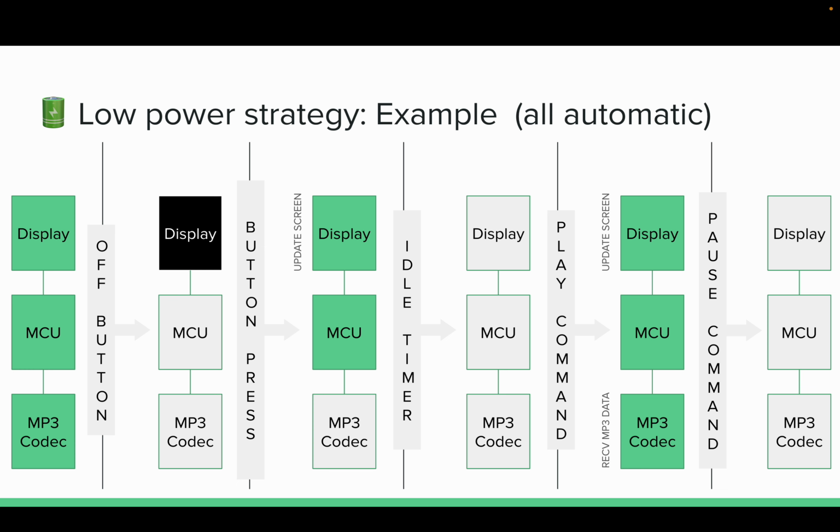Basically, it updates the screen. The act of trying to update the screen will do the work of the driver going, hey, we need to reinitialize the screen, and then update the screen so that it shows this new image. And then after that, some idle timer hits, and the system goes back into idle. It's no longer powered off, so display still on. But the display can be put into a low power mode. The MCU can be put into low power mode, so could the MP3 codec.